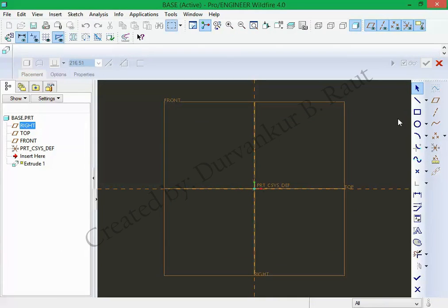I also have told you so many times to create the extrude first, and inside the extrude you must create the sketch. Why is it necessary to follow? Because if you create the sketch and then try to extrude it, many a times, no, anytime, it does not give you any error. It just shows you that it cannot create extrude. But you never get to know what is exactly happening. Why is the extrude not possible?